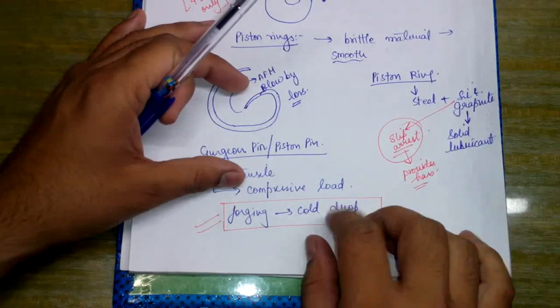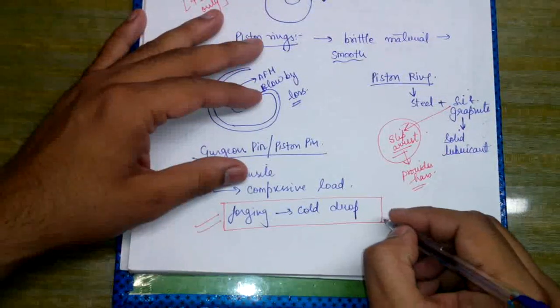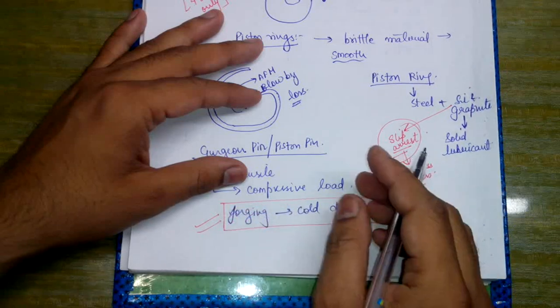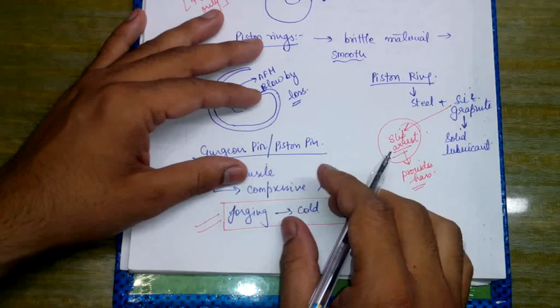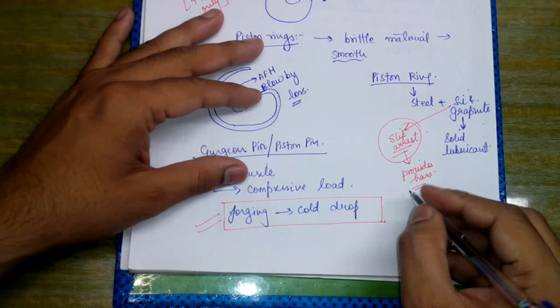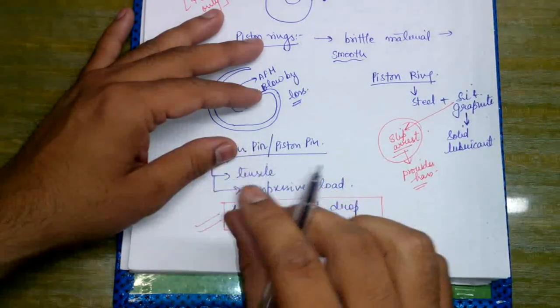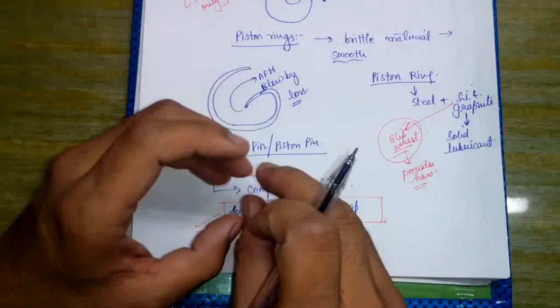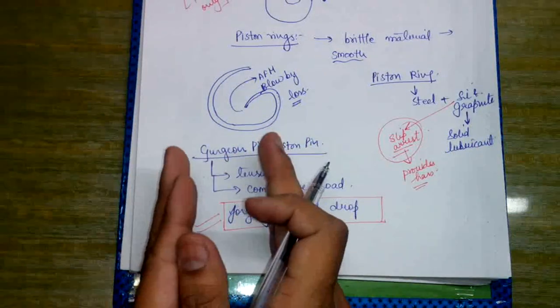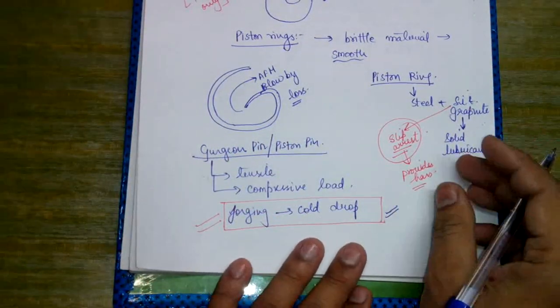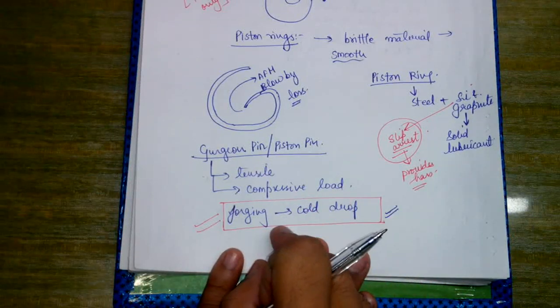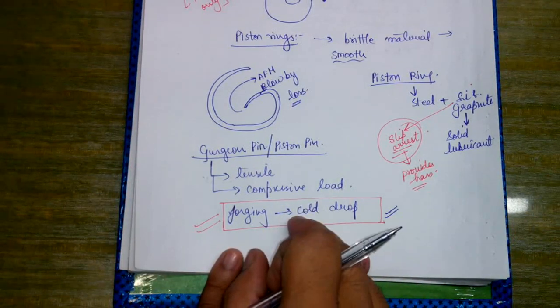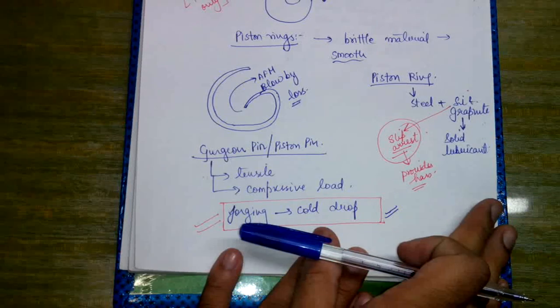इससे जो component produce होता है उसकी strength बहुत ज़्यादा होती है, और हम लोग इसमें कोल्ड ड्रॉप फोर्जिंग लगाते हैं. और इसमें यहाँ पर कंप्लीटली रिवर्स स्ट्रेस लोडिंग होती है, क्योंकि कुछ पार्ट में टेंसाइल स्ट्रेस आएगा, कुछ पार्ट में कंप्रेसिव आएगा. तो इसीलिए हम लोग को यहाँ पे स्ट्रेंथ बहुत ज्यादा चाहिए, और स्ट्रेंथ जो हम मैक्सिमम ऑब्टेन करते हैं, it is in the case of cold drop forging.